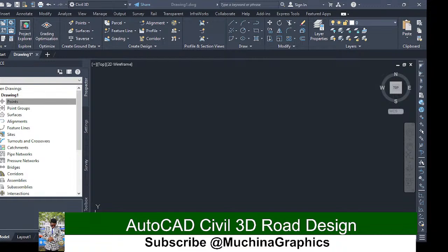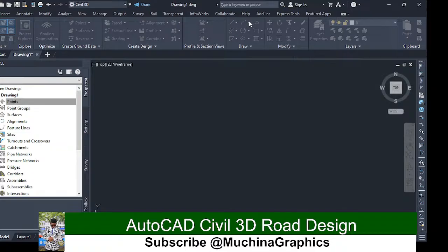So that being said, let's continue. After importing your points, remember to click the zoom extent. So let's click the import here. You get to select your topo survey points, and then you click open. When there, you change the format to PNEZD comma delimited, and you click OK.